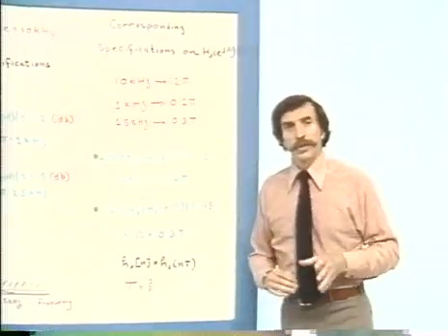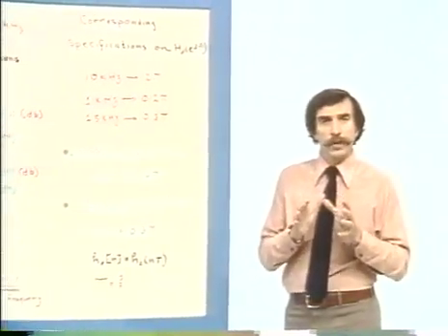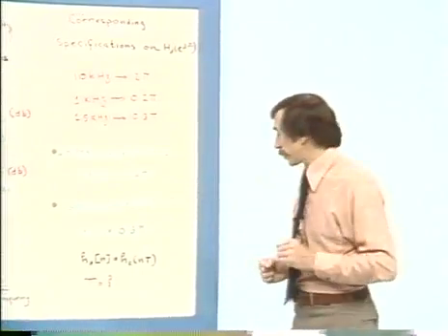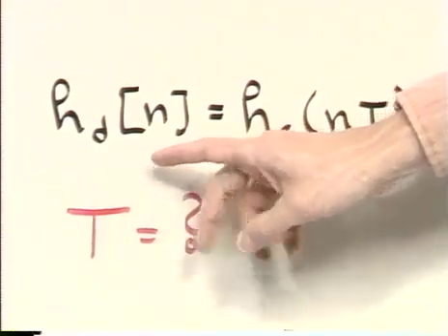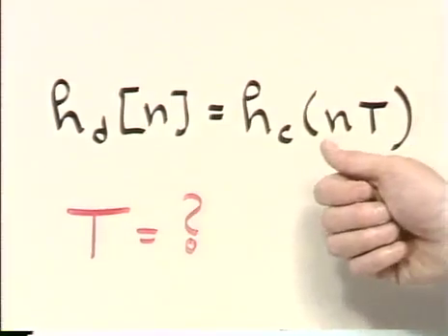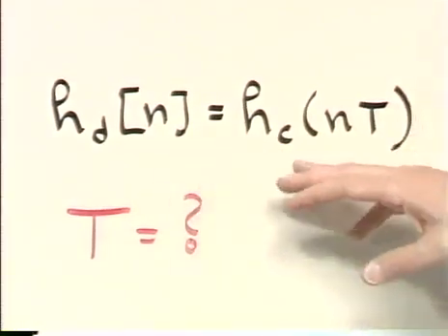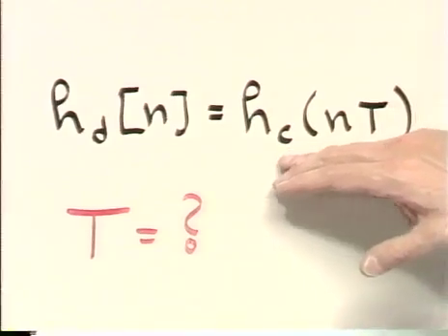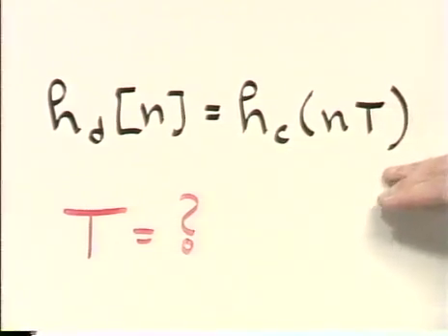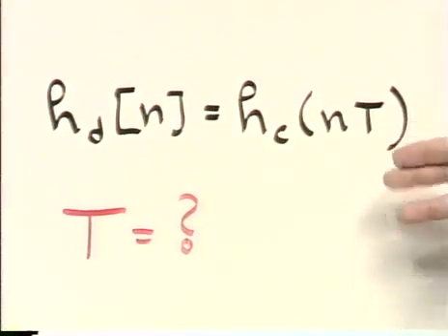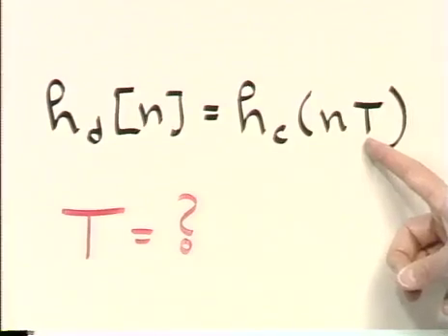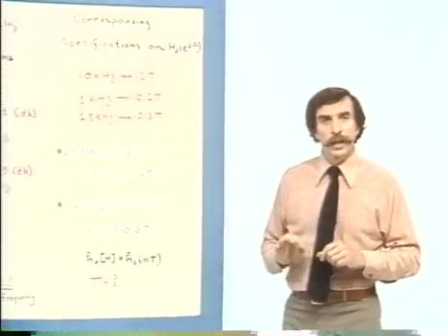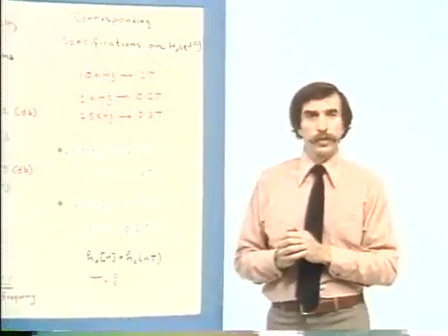And we now want to design the discrete time filter using impulse invariance. Now, in impulse invariance, as you recall, it corresponds to sampling, generating an impulse response, which is a sampled version of the continuous time impulse response. And there is a temptation naturally to think of this parameter capital T as necessarily identical to the sampling in the system in which the filter is going to be used.